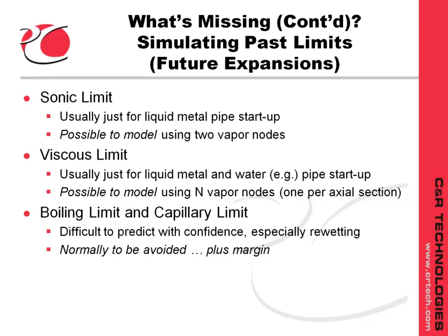Probably the first thing that people new to heat pipes learn is a set of common transport limits such as sonic, viscous, boiling, and so forth. So they're usually a little surprised to see it all condensed into a single power length product, QL effective, in FloCAD, since that's often focused on the capillary limit. This simplified treatment of transport limits could be revisited in the future.